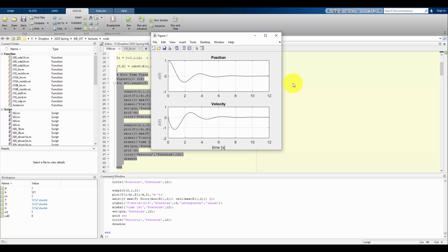So back to its equilibrium position. And velocity, we're going to see it does start at 0, but because of that initial stretch of the spring, it's going to increase. The mass is going to travel vertically upwards by the definition of our degrees of freedom, and the velocity too is going to die out because of that damper. Eventually the system comes to rest, 0 position, 0 velocity.